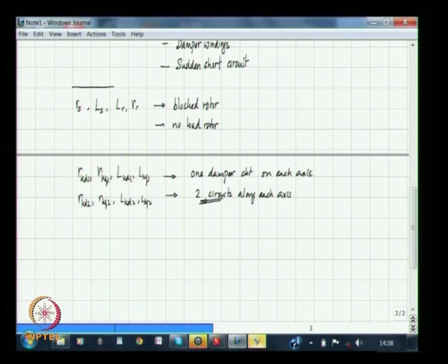All along we had assumed that saturation is neglected, but this may not be acceptable, especially if one is going to study the response of systems to very large excitations or large disturbances. One can't really design a machine such that it never goes into the area where iron gets into saturation.